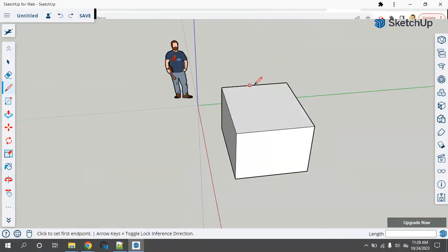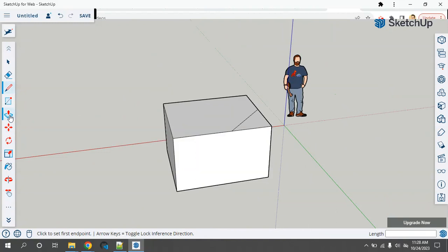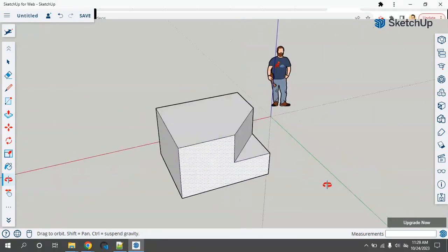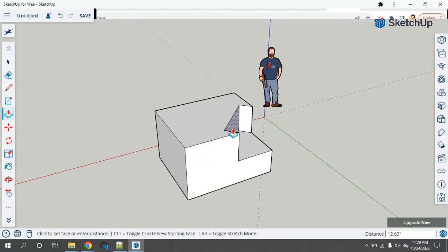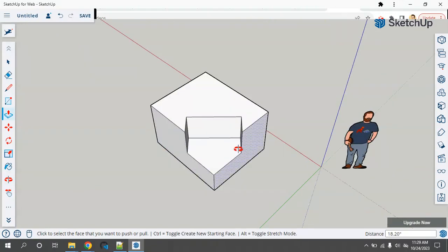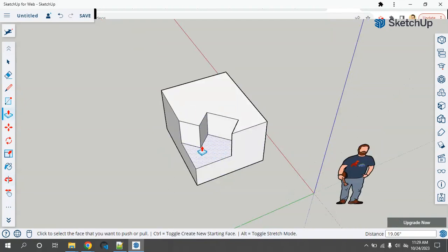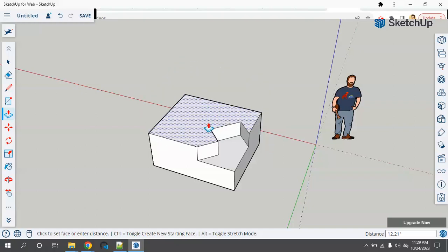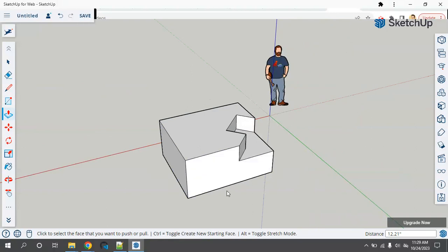What I wanted to look at was being able to, say, draw lines from one part to another. In this case, I've drawn this little triangle at the edge here. And if I then grab my push-pull, you can see that I could step this down. I could pull something up or push it down to start to create little nooks and crannies and wedges and things for putting things together. And you can see we can very quickly start to create some interesting looking shapes. Whenever we've got a face there, we can push or pull it down to extrude or to subtract some things.